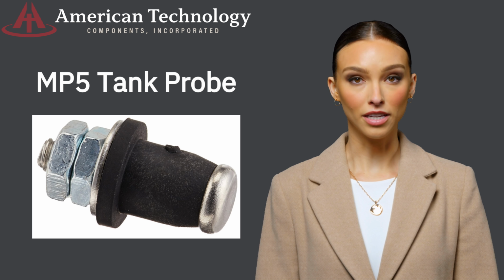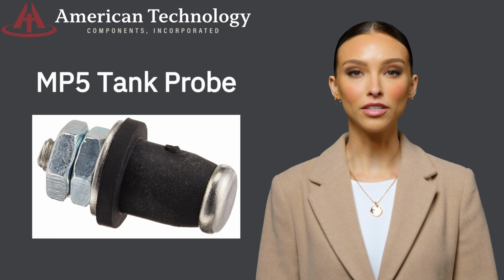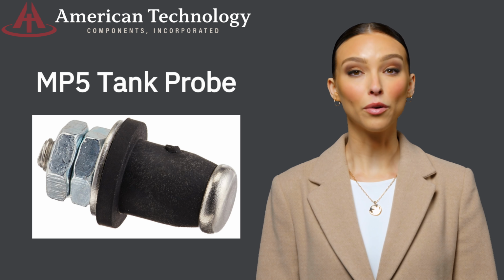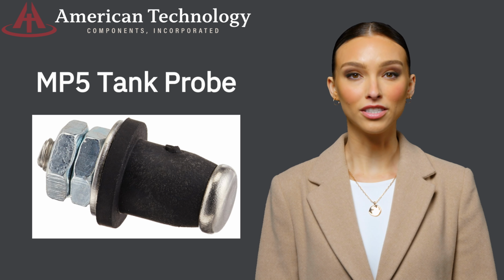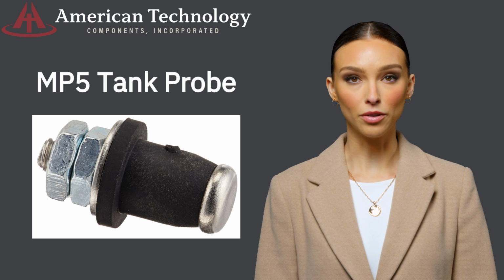an inability to conduct electricity, a buildup of materials within the tank resulting in a path for current to go from probe to probe regardless of tank level, an improper installation of the probe, such as not installing the probes at least 10 inches away from the ground probe, are all reasons for failure associated with the MP5 tank probe. This component is not a sensor and has no intelligence installed that can be compromised. It is a bolt made of metal that is used to conduct electrical current.